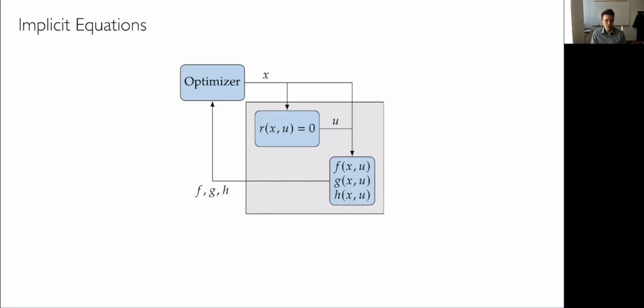There are some implications of this that we'll talk about later on, but some that we've already discussed today is that because we have this, as compared to regular analysis, we need to make sure these loops converge really tightly so we don't have noise. We need to make sure we're using efficient solvers so that our optimization isn't taking too long, because we're not going to run this just once, but many, many times. And if we want to get derivatives, there's some additional things we need to think about here, which we'll talk about later in the semester.